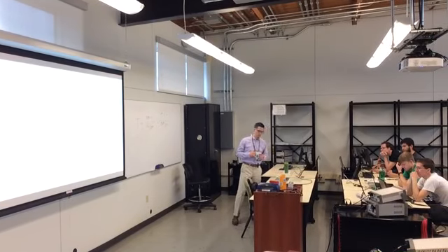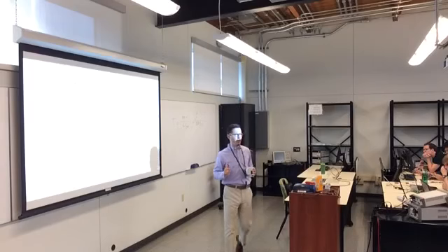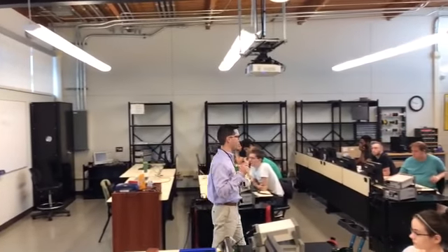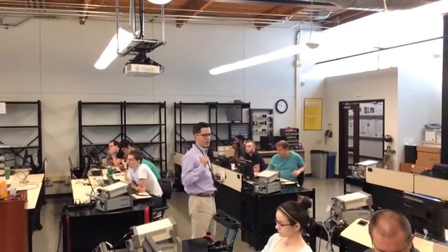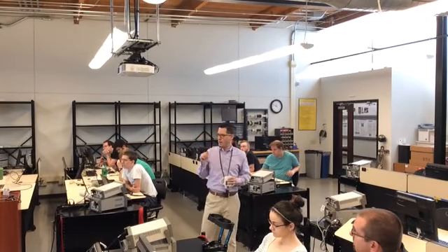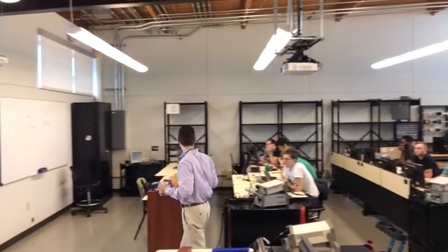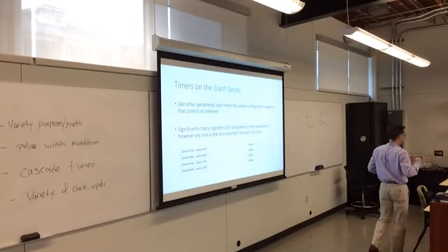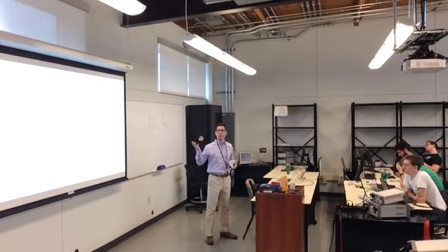The timers on your processor are just like any other peripheral, meaning that they are memory mapped. They have a certain space in memory in which they live. These timers actually have way more configuration registers than a lot of the other peripherals. There are 34 registers across all of the timers. That's a lot. It's a lot because there are a lot of different modes for these timers. We covered 4 or 5 of them. There's probably 2 or 3 more.